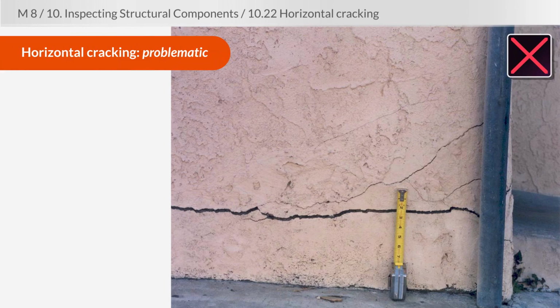This is horizontal cracking. It's almost always a problem, and you should always report it. There's some type of movement going on, probably in the soil, along the foundation, some type of lateral movement that's causing this to essentially buckle in.